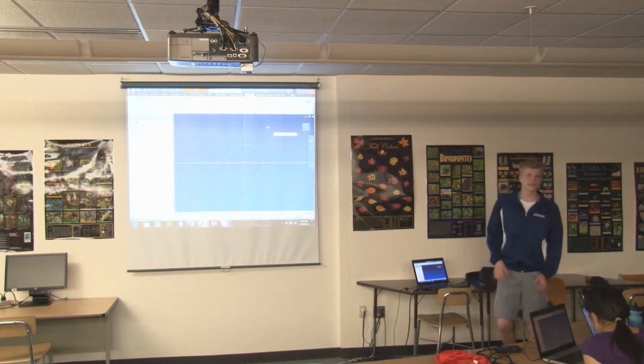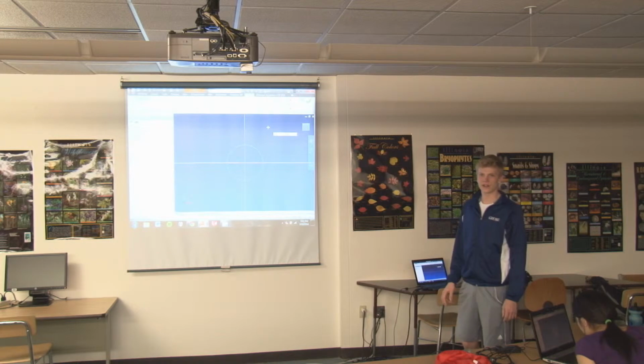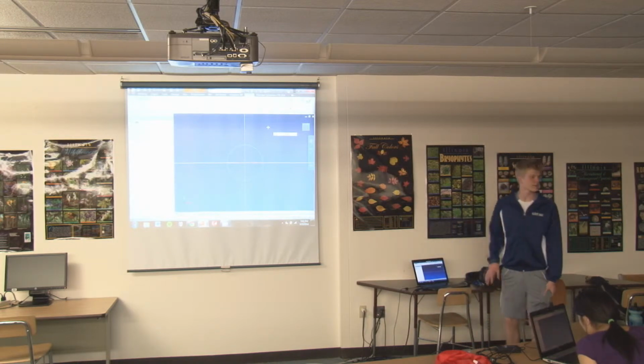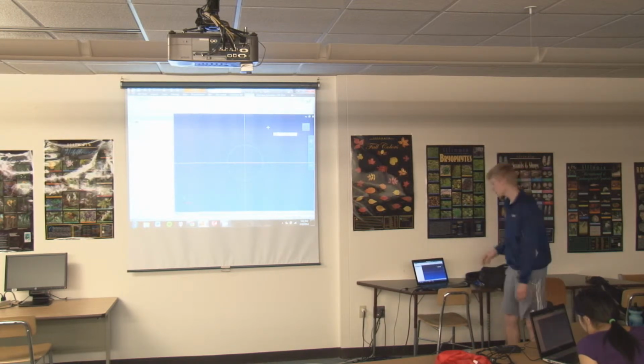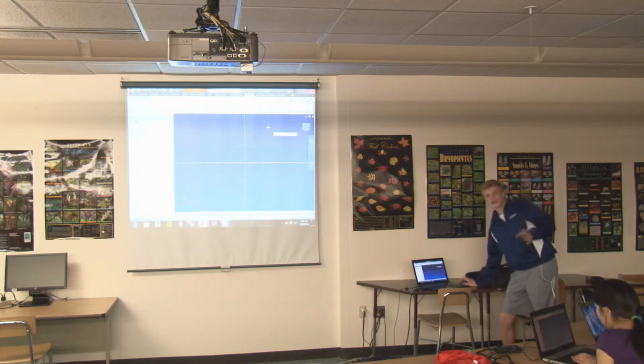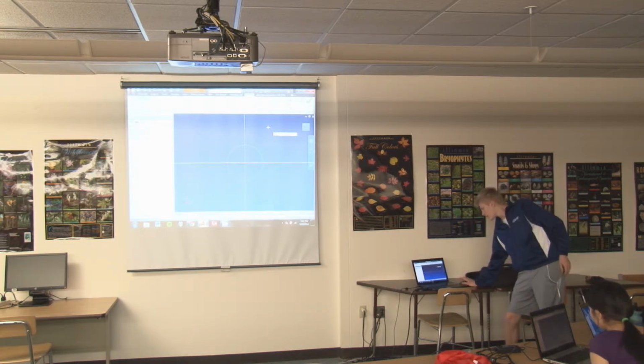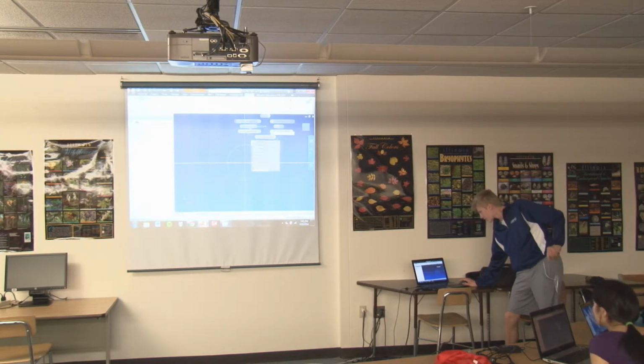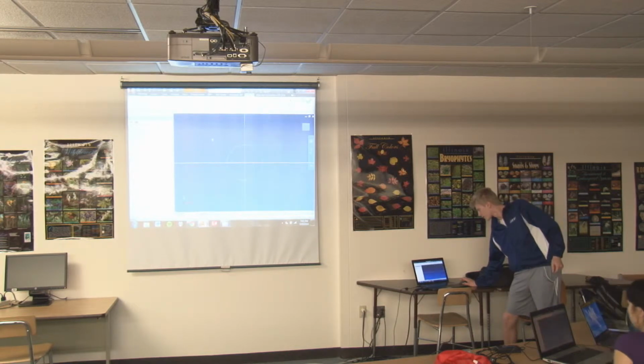Now, one of the most useful things in Autodesk is your right click. You can enter a number of smaller submenus from the right click button. Generally, the easiest way of doing it is whenever you want to clear what tool you're using. If you hold the right click and then drag over to whatever of these options you want to go to, you can cancel the tool that you're using right away just by right-clicking and dragging to the cancel button.